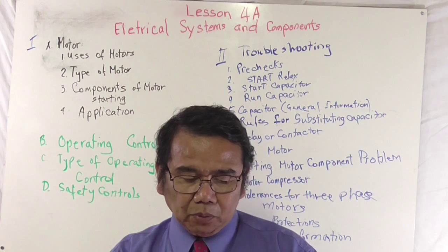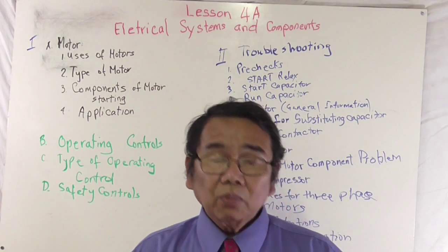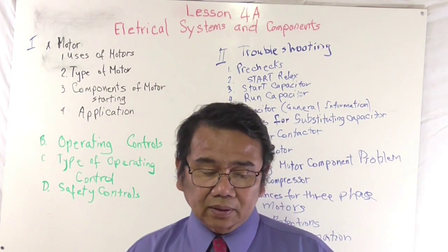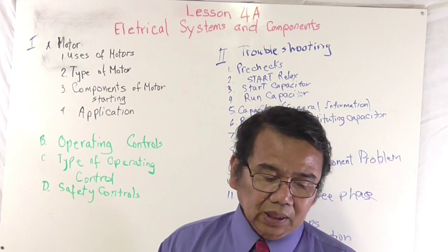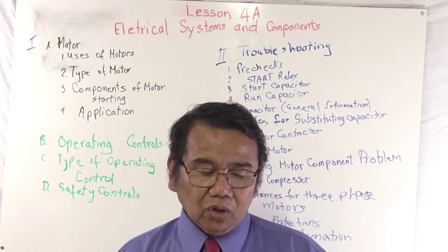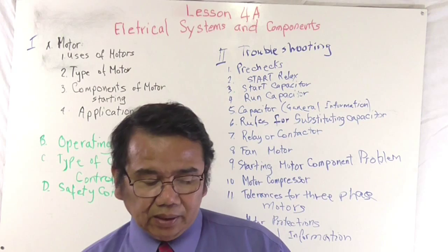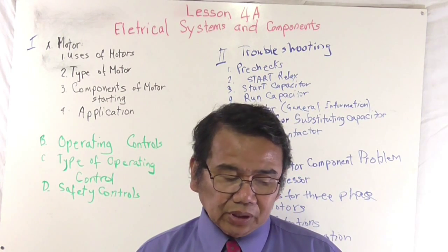And then if it's a starting components problem, you've got running capacitor open: motor may or may not run. If it runs, the current will be higher than normal. And running capacitor shorted: overload will trip because the potential start relay and start capacitor short out of the circuit.